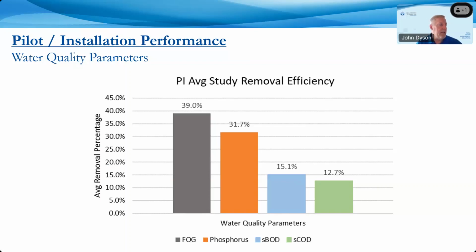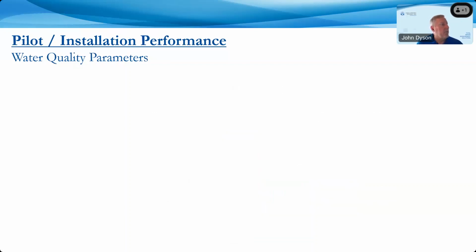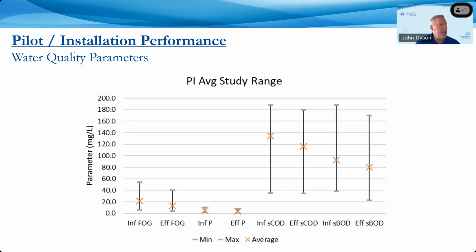And we actually see fractional soluble amounts of BOD removed. I really think this is colloidal material that we remove through the filtration process, that when you filter a raw sample for soluble BOD, you do still have some colloidals that do pass through. And we have the data for the range of information and how they may vary there too.